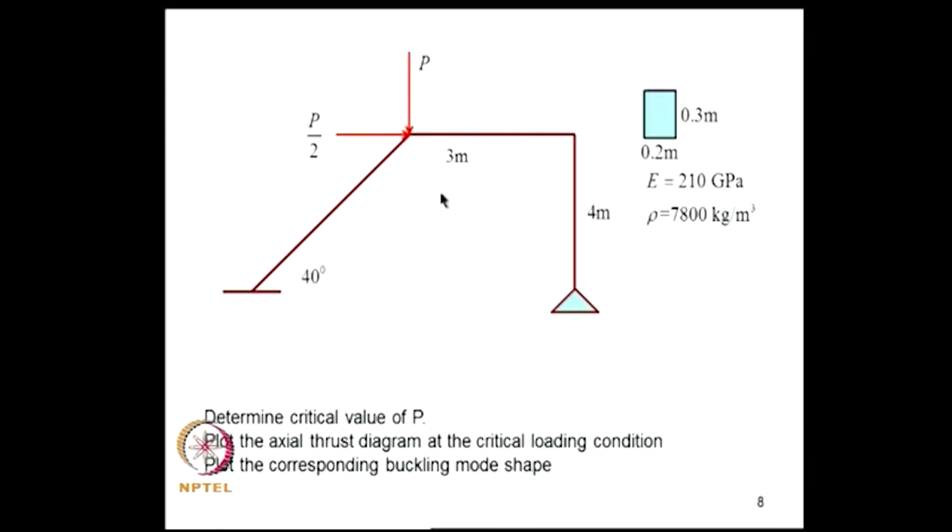If you go back in your lecture notes, to one of the earlier lectures where we studied the vibration analysis, we have analyzed the same structure. So, the elastic stiffness matrix is already available. You have to follow the same steps, but assemble the geometric stiffness matrix and perform the eigenvalue analysis.